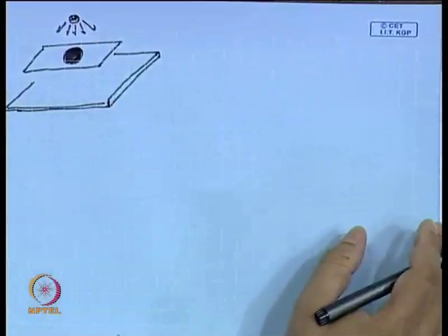That means, if this polymer is exposed to light of certain wavelength, it becomes soluble to certain solvent, or it could be otherwise. Originally it was soluble to a solvent, but after the exposure this solubility is lost. So, it could be either way. That means, this polymer is sensitive to light.